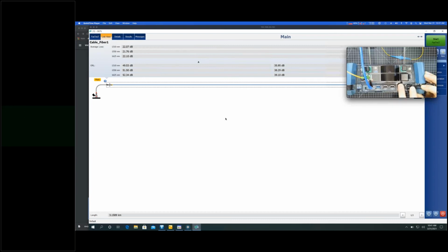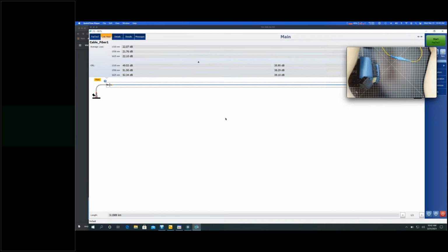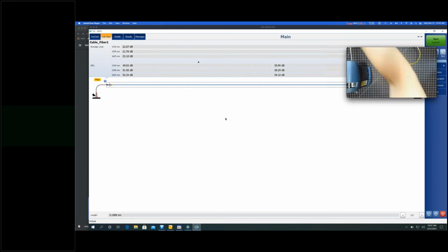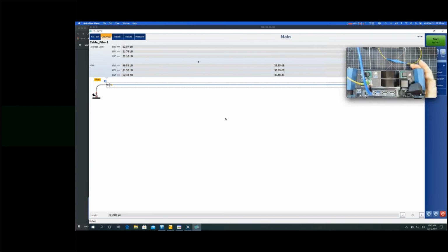And these can become really handy for doing exactly what we did with this power meter, the PX1 and the FLS 300. The problem is I can't move these two pieces of equipment to two different locations. However, in a pinch, I could use a loop up cord and test two fibers to see if I'm getting any high losses on either one, then switch the ends and test in the other direction to see where the loss is on that. So realistically, what I wanted to show here is just how to do this in a pinch.